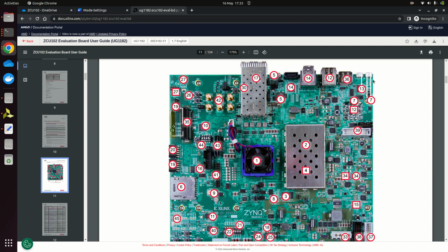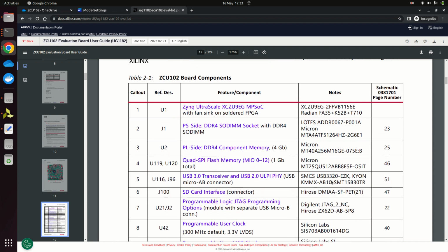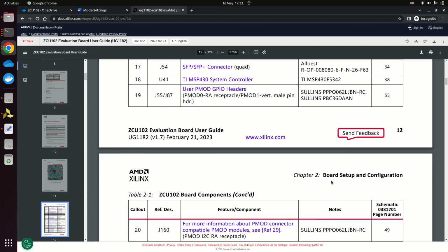If you are using it as a processor and you want serial communication with that processing and the image in it, then you will be using this UART. We are now programming our FPGA, so we will be using JTAG here. So we are going to use this port, which is called JTAG. Now coming back to these LEDs and switches, let's see if we can find it out.